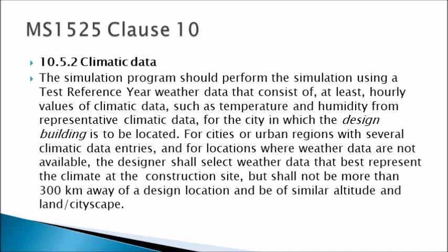So most of all of the software programs, the building simulation programs, will allow you to choose weather data of your choice. So it is important for you to find reliable weather data. So it is not acceptable, for example, if you design a building in Kuala Lumpur, but to do the simulation you use weather data of Bangkok, or even Seoul. So it will not reflect the actual performance of the building in the climate.